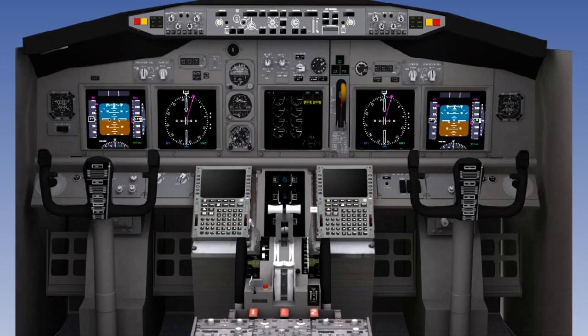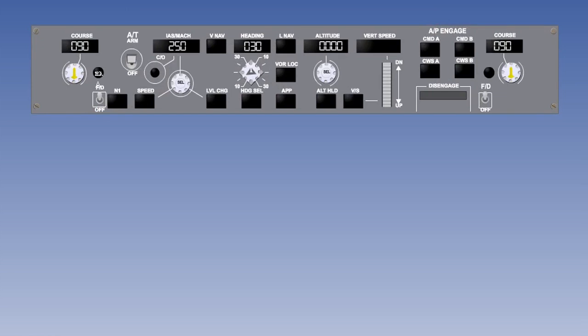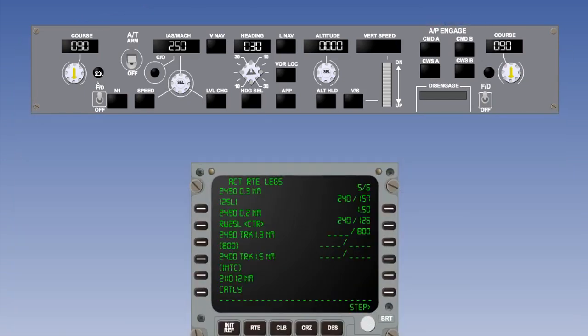Before we look at the departure, let us look at the instruments we will be using to set and display the flight director information. Firstly, to set the information onto the flight director system, we have the mode control panel and the flight management system. The flight management system affects lateral navigation, LNAV, and vertical navigation, VNAV. These are selectable pre-programmed routes and vertical paths for the flight director system to follow, although for the majority of this lesson we will be concentrating on the mode control panel inputs.